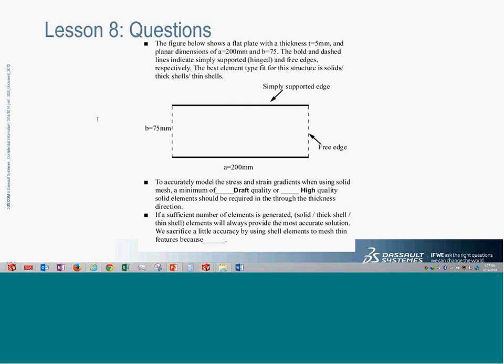But that argument, here luckily, it is 200 by 5. But it could also be, why not, 75 by 5, and look like a comparatively thicker geometry. So it's 15 over there, and it can lead to thick also. So just out of experience, I would prefer a thick shell for this particular geometry.